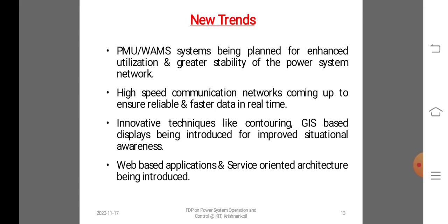Some other points for these new trends are: contingency analysis assesses the impact of a set of contingencies on the state of our system and identifies potentially harmful contingencies that cause operating limit violation. Optimal power flow recommends controller action to optimize a specified objective function, such as system operating cost or losses, subject to a set of power system operating constraints.